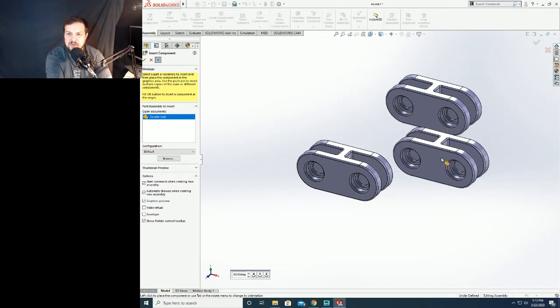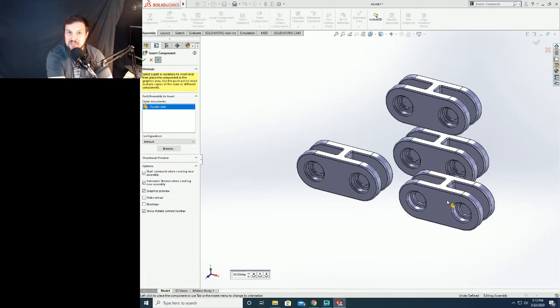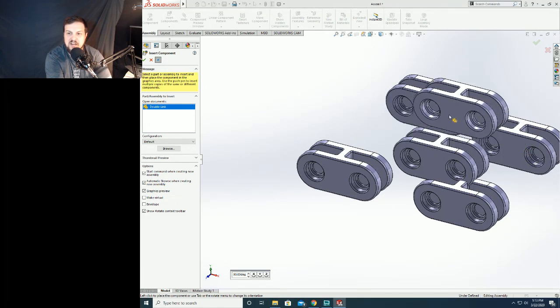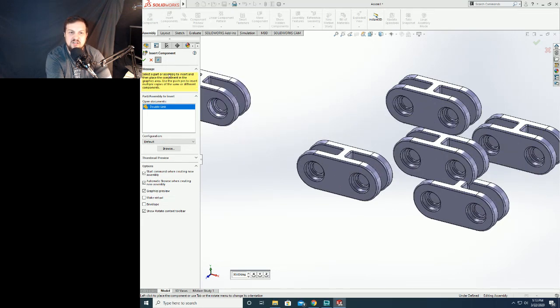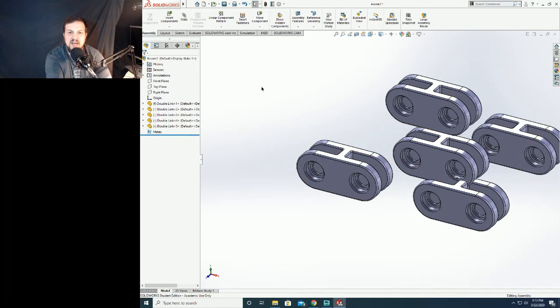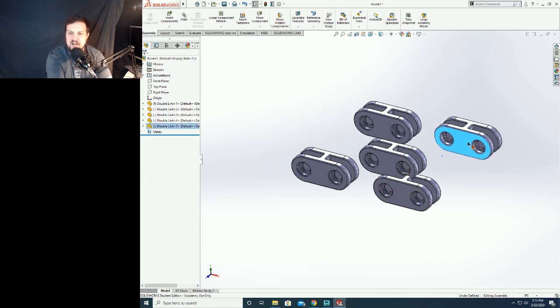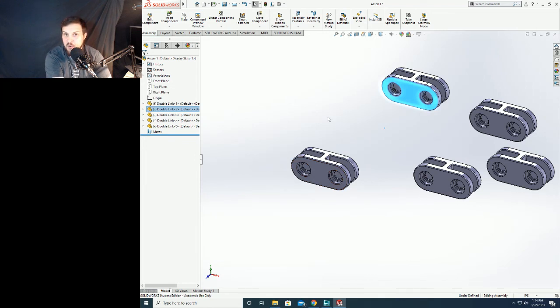I'm going to click once. You can see as I click once, it dropped a component, but it didn't exit the tool. I'm still inside the tool. So now I can click again, it dropped another component, but I'm still inside the tool. Now I can click one last time. Now I've got 3 additional pieces out there, making us 5 total, including our original. And now I'm just going to hit my red X to exit the tool, because if you hit that green check mark, it's going to drop one over the origin, remember? So now I'm out of the tool. I've got my 4 additional links to my first one, and that is it for dropping the original components. So go on to the next video if you are ready to continue past this point.